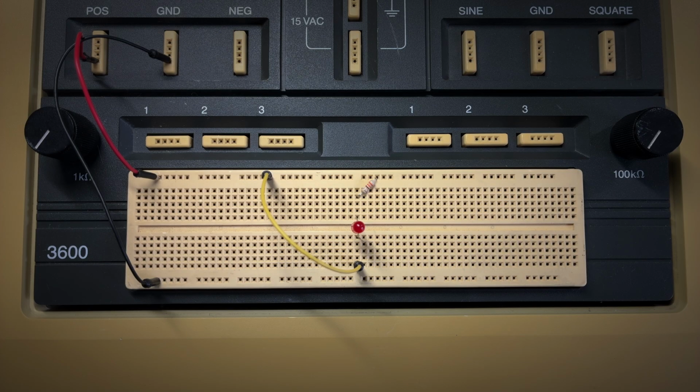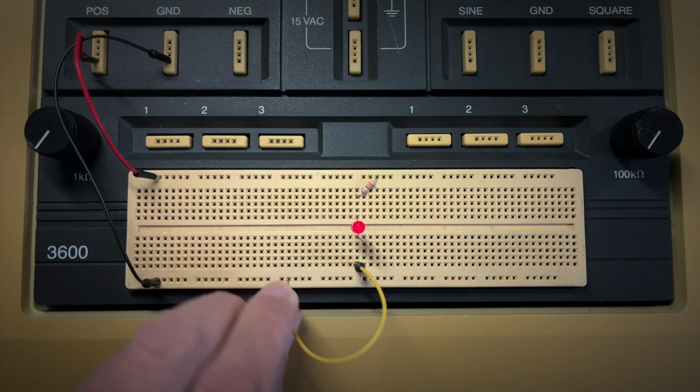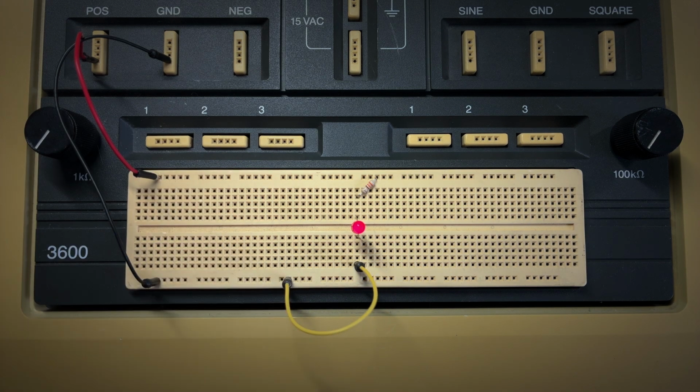In that position, both legs of the LED are at the same electrical potential, so no current flows and the LED turns off. So counterintuitively, the LEDs in the Hero Junior are wired in just this way, so that you turn them off by sending a logic 1 and turn them on with a logic 0. And this tiny fact helps to explain why the lights in the Hero Junior's phoneme playback do not look correct.